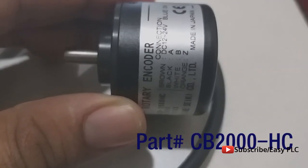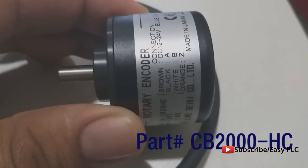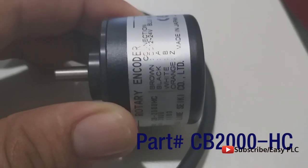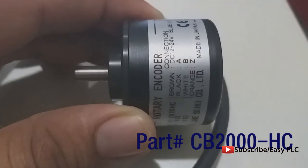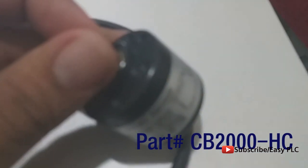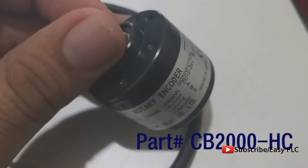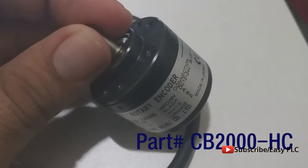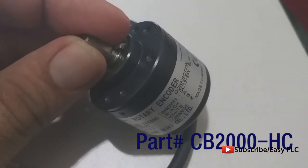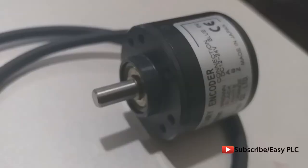Let's start today's session. We have a rotary encoder with 2000 pulses per revolution. As you can see, it has black, white and orange output wires as A, B and Z phase outputs. We can program the PLC to count encoder pulses as it rotates clockwise or counterclockwise. By counting its pulses, we can use it to measure the speed of the motor or distance traveled by an actuator.